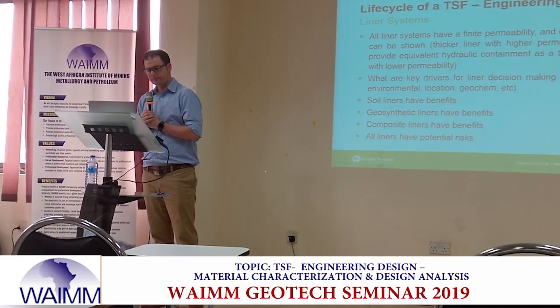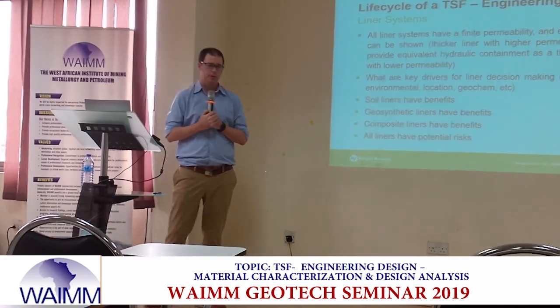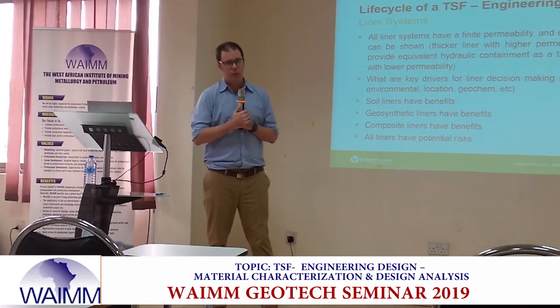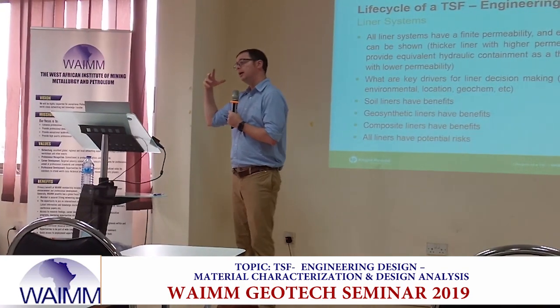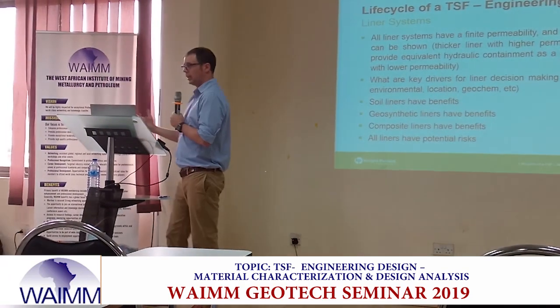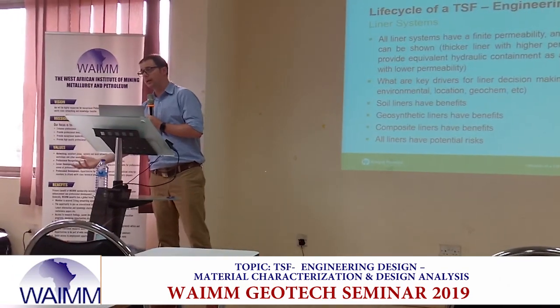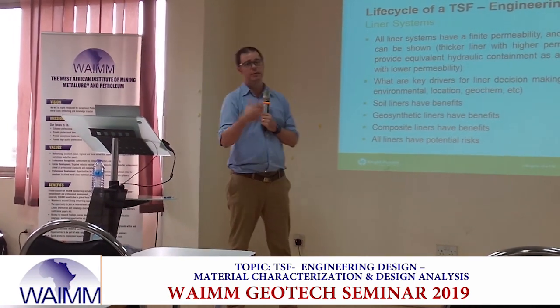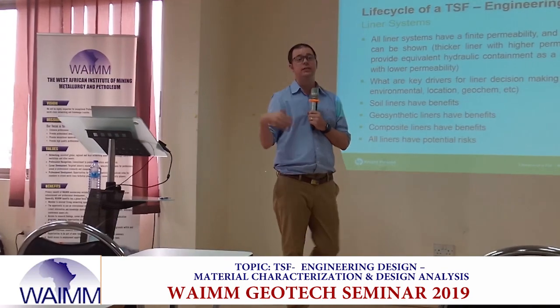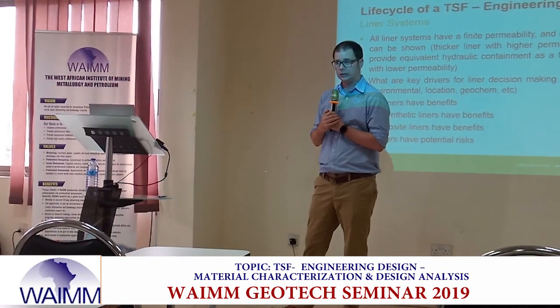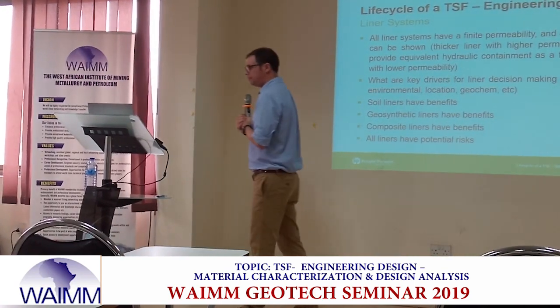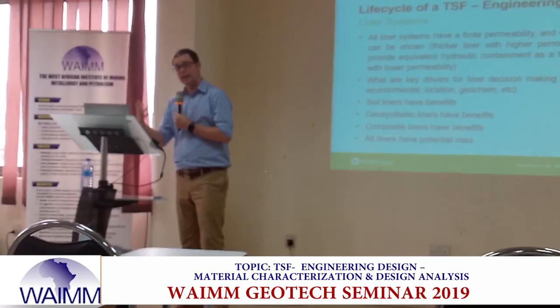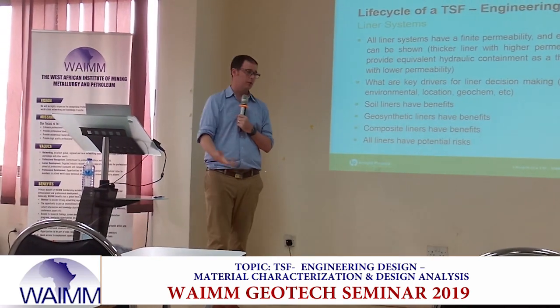Okay? Maybe there's a geochemical issue. For instance, if we were to put something in that might geochemically interact with the clay, maybe that's a positive thing, but it might also be a negative thing. We might have something called sodium exchange, where we might actually increase the hydraulic conductivity of the clay. So it all depends. The same thing with the HDPE geomembranes, right?